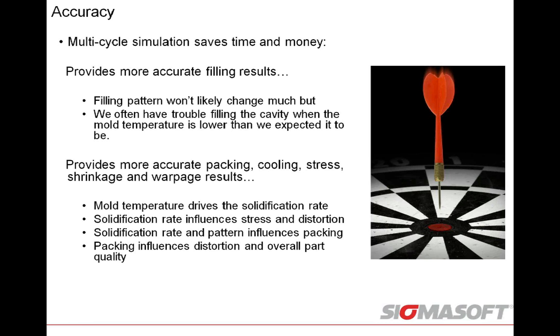But if you were to run that mold through, say, 20 cycles, you'd see that the temperature is drastically different after you subject the cavity to 20 cycles of hot polymer being injected. All of a sudden a warmer mold temperature might allow you to fill that part. So you might have an inaccurate prediction, where the simulation says you have a short shot, but in reality you don't. Again, multi-cycle simulation gives you that better accuracy.